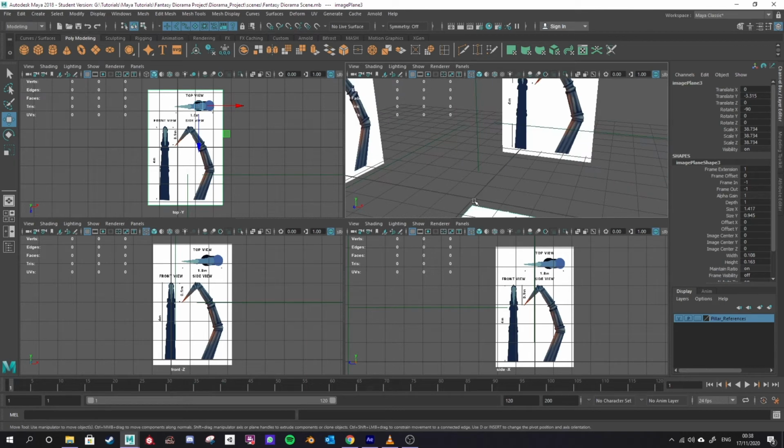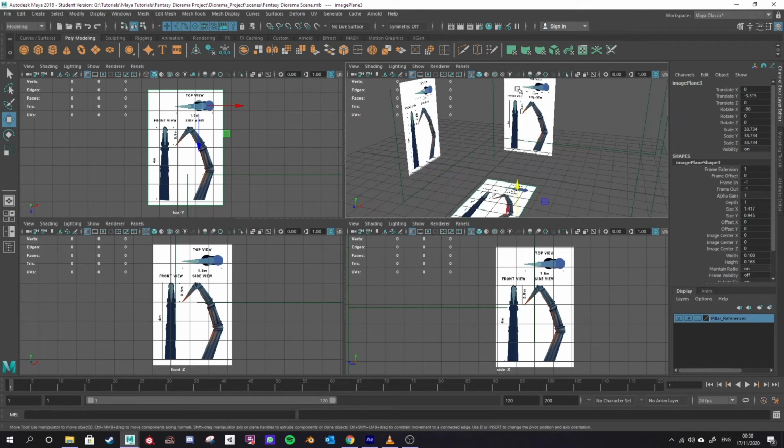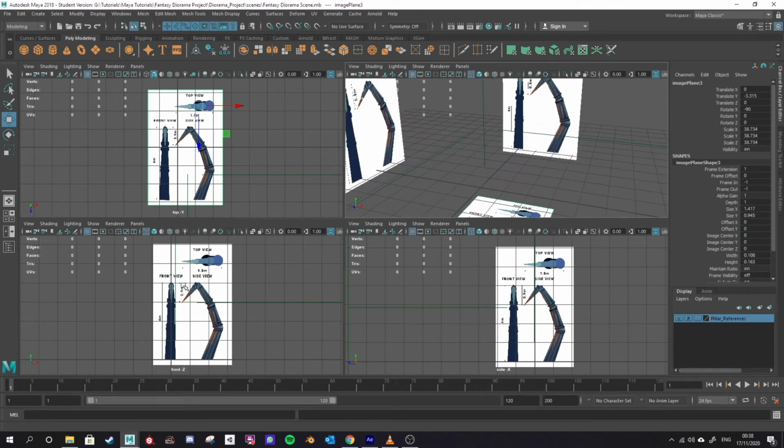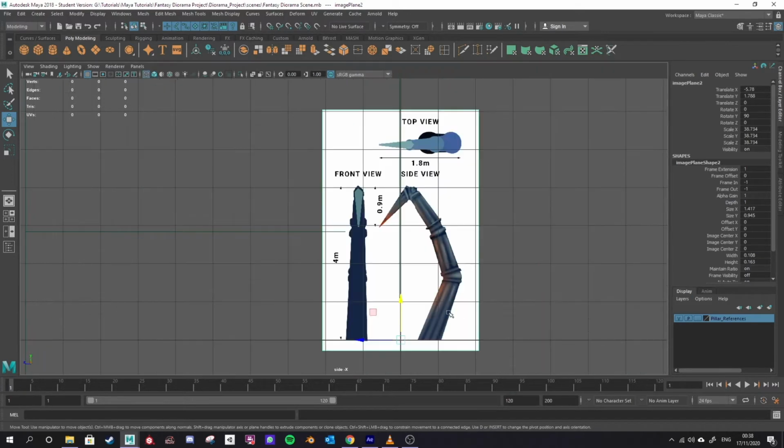So you can see I've got 0, 0 lined up with the post in the front view, which I did just earlier there. I'm now going to set the midpoints of the other views and move them so that they are also centered. So let's look at the side view first of all. If I press D to select my midpoint, I can move that across right into the center of the side view base, which is where I want to start modeling from.